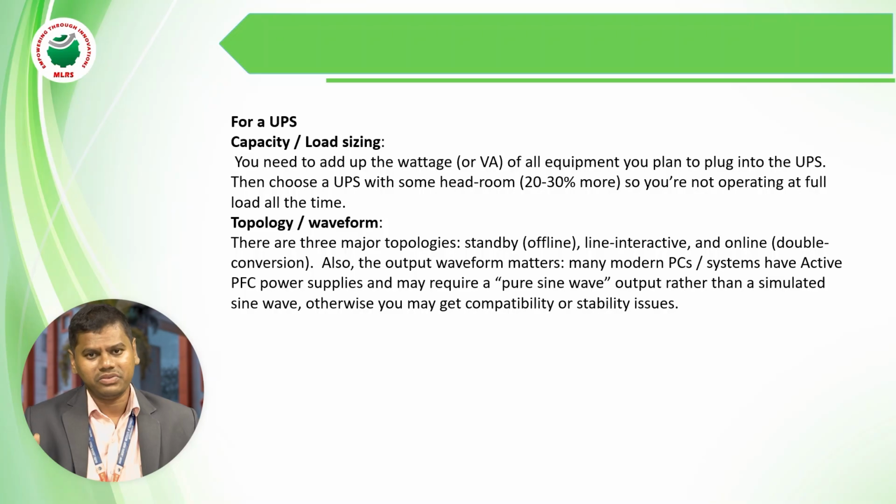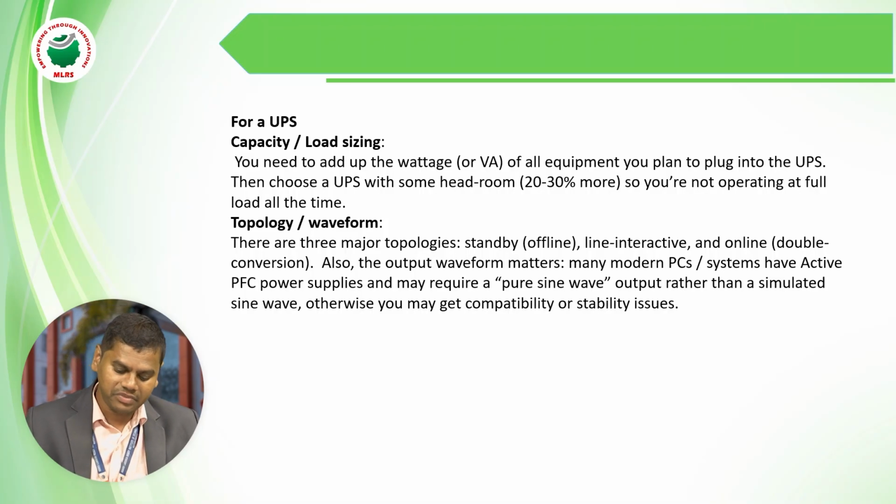Suppose you need a UPS. Check the wattage or volt amperes of all equipment to plug into the UPS. Then choose a UPS with some headroom, 20 to 30% more than that.